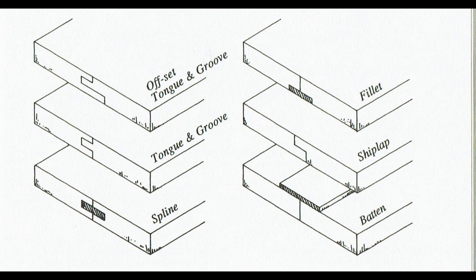Now, the advantages, obviously, of doing some of those specialty joints would be the increased strength, which makes them long lasting, or it could be a decorative piece, and they resist a lot of forces pretty well. However, they can be, again, very time consuming, such as just the amount of time that it would take to hand cut a lot of those joints, especially in the dovetail. Would require a lot of patience when it comes to working with that particular joint. Now, there are some specialty tools that do expedite that process, but they aren't commonly seen in most shops. So if this is a joint that you were looking to do, you would most likely have to spend not a major fortune, but a decent bit of money in order to make it a little bit sped up in that process.